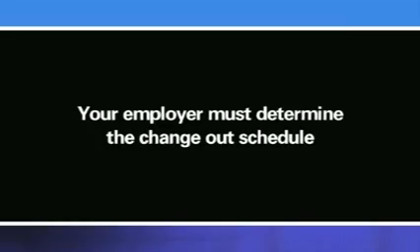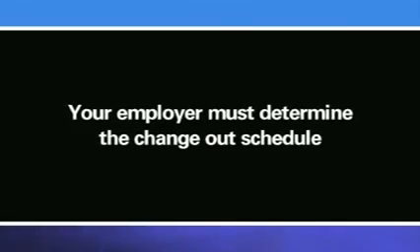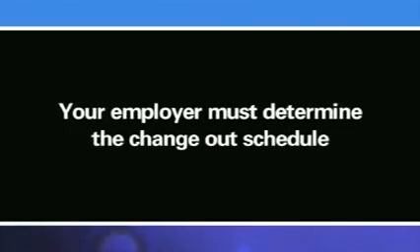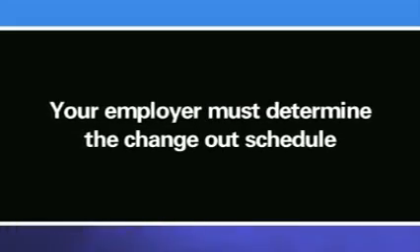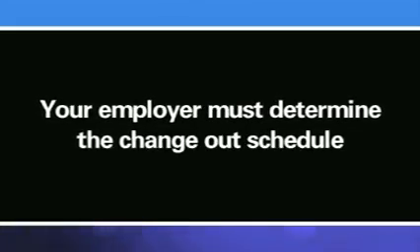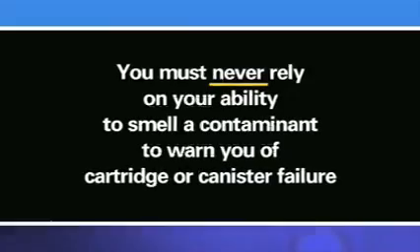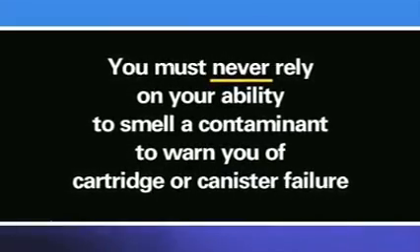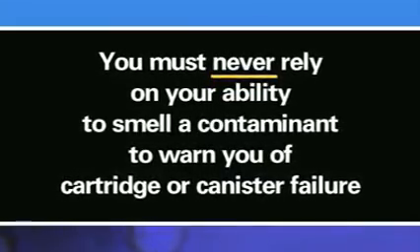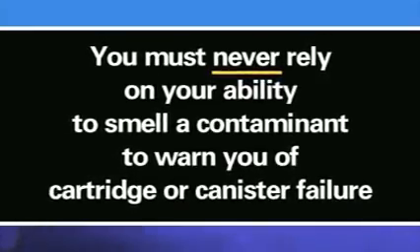This schedule for replacing worn-out cartridges or canisters is known as a change-out schedule. Your employer is responsible for providing this information to you. Remember, you must never rely on your ability to smell a contaminant to warn you of cartridge or canister failure.